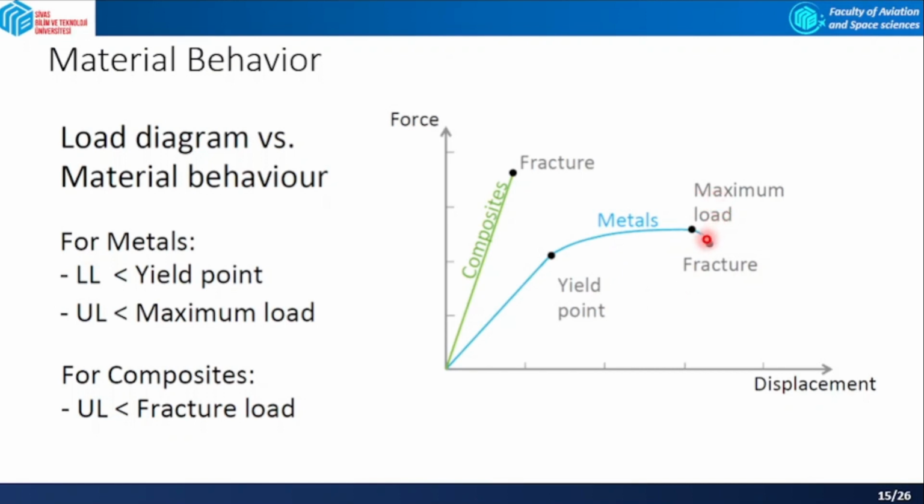Comparing these material behaviors with the definitions of limit load and ultimate load, you can infer that the limit load should remain below the yield point. Okay, here is the yield point.